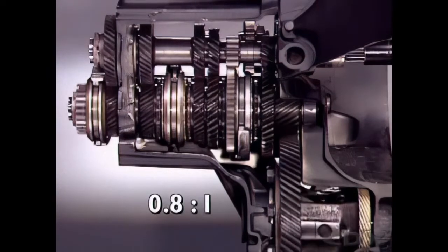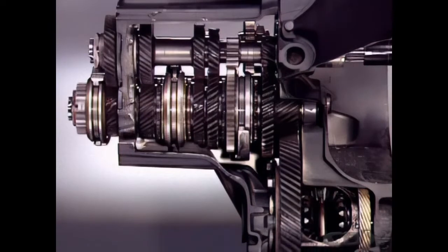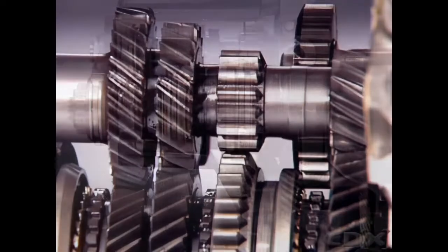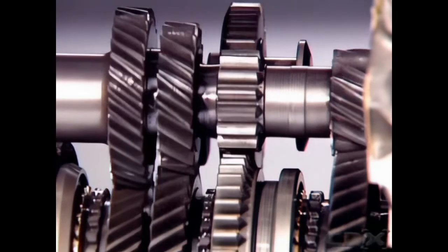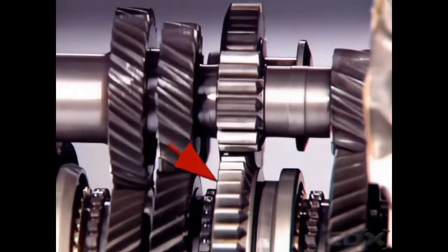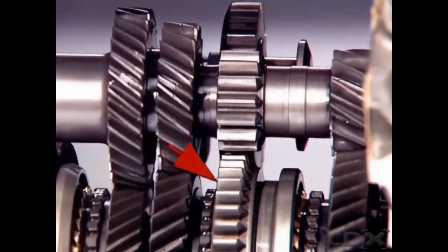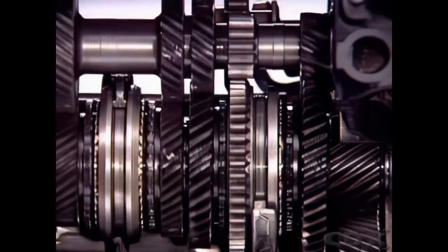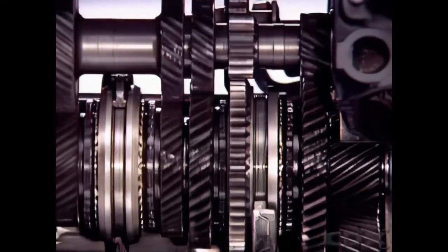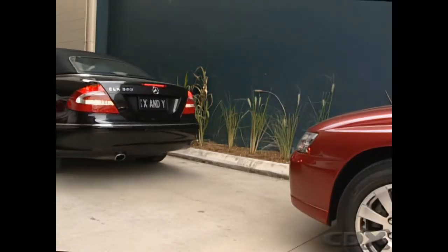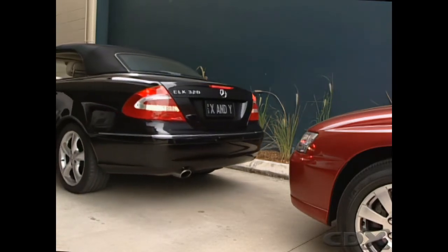This is often an overdrive ratio, with the driving gear larger than the driven gear, making the driven gear rotate at a higher speed. For reverse, the reverse idler moves to mesh with a reverse gear on the primary shaft and the matching gear teeth on the outside of the first and second gear engagement sleeve. Drive transfers through the idler to the spline secondary shaft sleeve. The idler between the shafts makes the secondary shaft rotate in the reverse direction. This reverses the direction of the final drive ring gear and the road wheels.